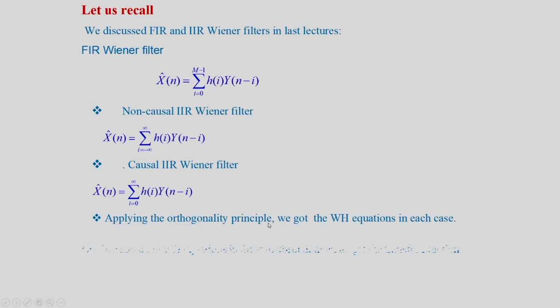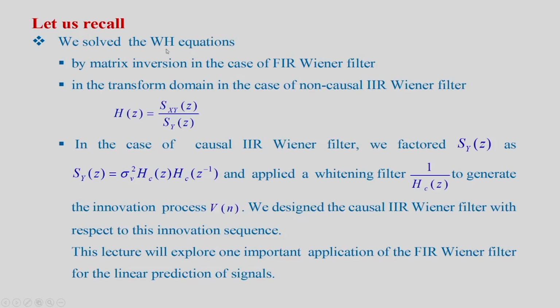Applying the orthogonality principle, we got the Wiener-Hopf equations in each case. We solved the Wiener-Hopf equations by matrix inversion in the case of the FIR Wiener filter.